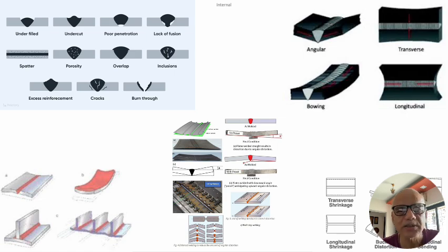If you don't have access, like in tubes, pipes, or some of the big shells where you cannot go inside, then the welder through his screen is able to judge whether the keyhole he creates while welding the root run is getting fully filled or penetrated.